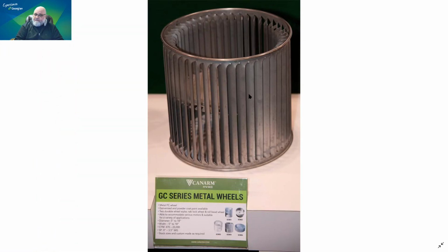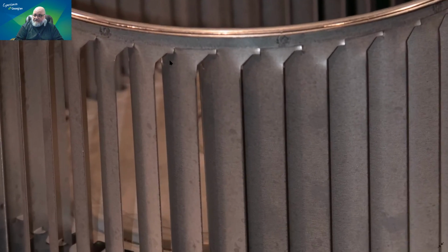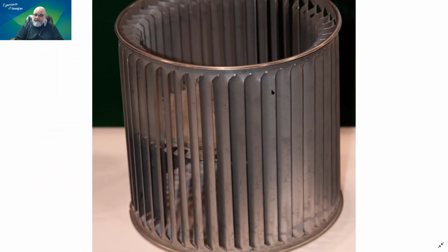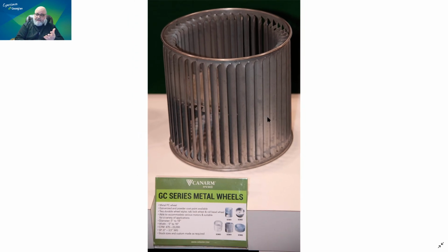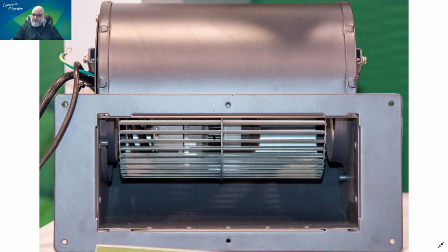So this is, as I said, easier to make. Look at it. It's just punched through, and I'm saying easier to make compared to the backward curved, not easier to make in general. But it is sometimes not safe to use in applications where you could possibly open up a space and provide it with more air, and then it will overload.